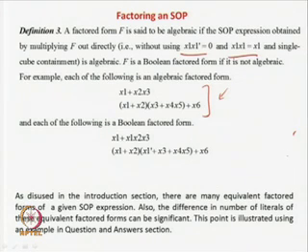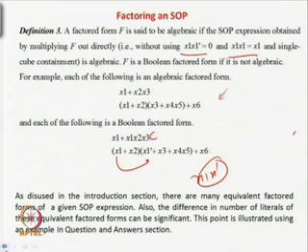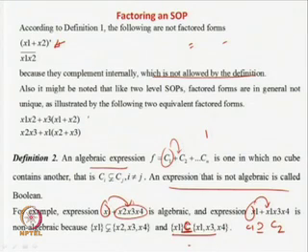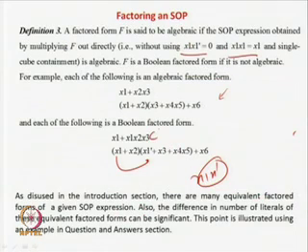The following is the Boolean factored form, because if you look at this, if you consider this as C1 and this as C2, then C1 will contain C2. So, in this case this is not algebraic. Similarly, if you open this one up, you will find that it is a non-algebraic factored form, because first you will find x1 prime, and this will actually kill you. So, just opening this expression and looking at definition 2, we will find that this is a Boolean factored form and not an algebraic factored form.